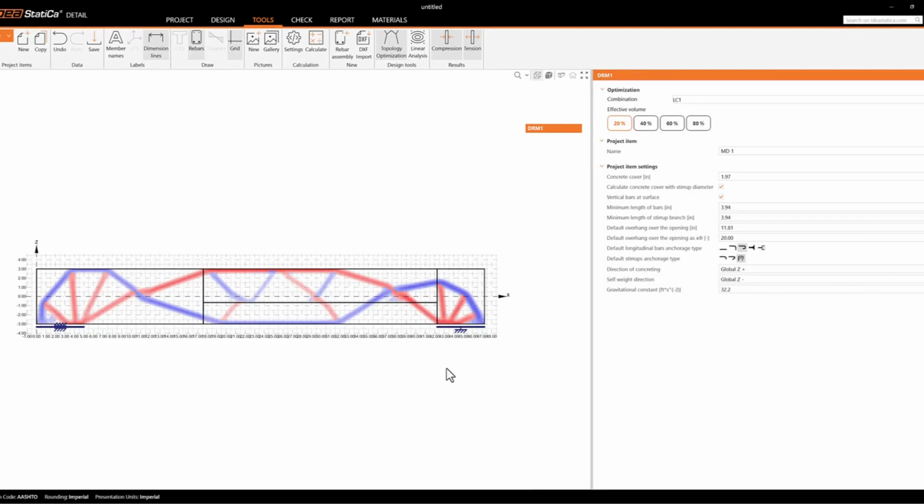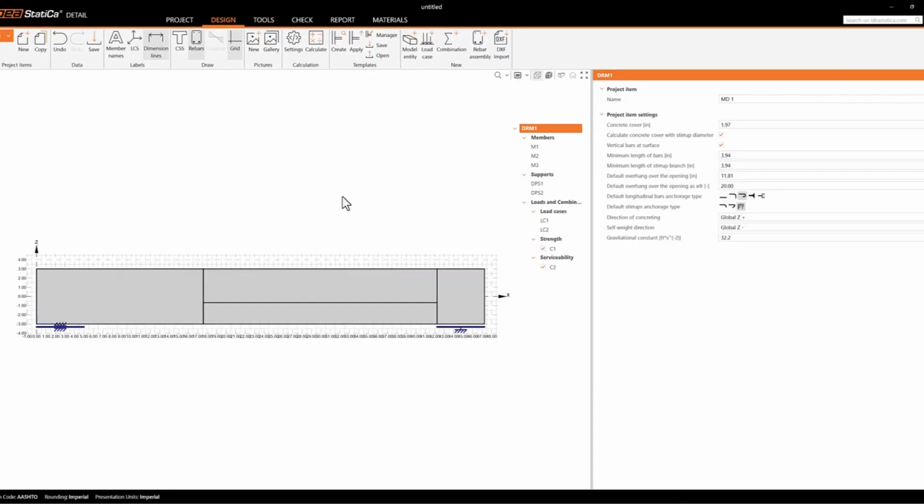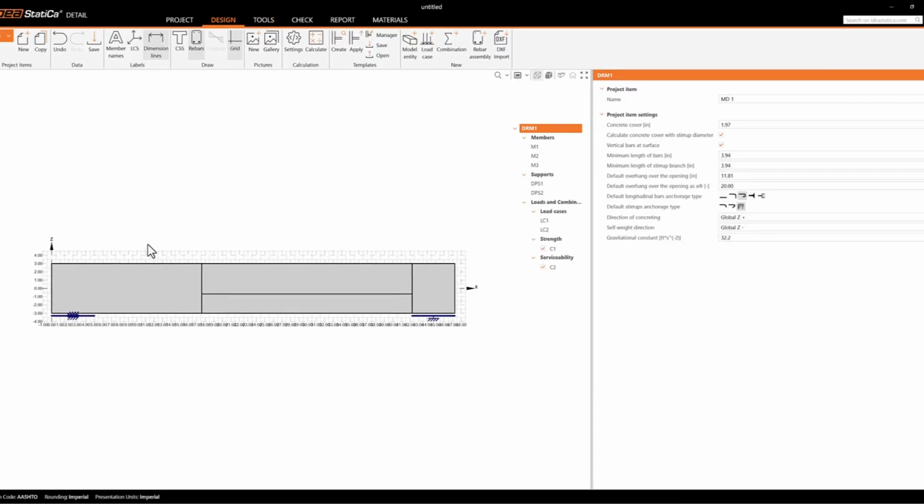So it will be something similar, but if you want to match and verify your strut and tie model, you should apply the forces exactly as you have them in that model, okay? This is just a quick note. All right, so once you learn how the stress flow is, remember, without considering the reinforcement, then you go back to the design tab, and now you can use that as an initial pre-design of the reinforcement, okay?